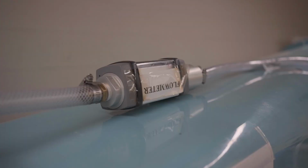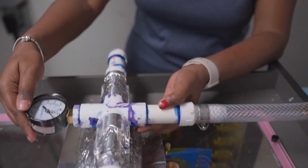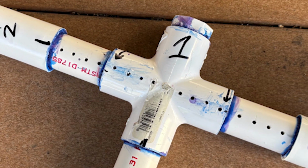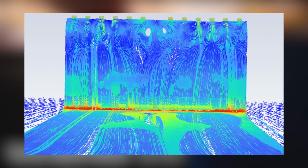The modular injector and the COANDA-directed geometries were developed in tandem with the secondary flow system. The SFS draws air from the AME lab supply and delivers it to a PVC T-bar. The T-bar has a series of 12 outlet holes to dump pressurized air into the injector plenum and transition it into a free-stream jet sheet.